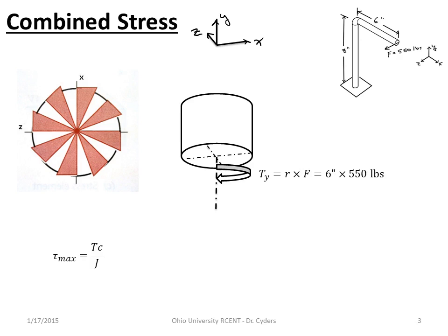And for a round shaft, circular cross section, the torsional stress distribution, the shear stress distribution due to torsion, is maximum at the outside. It is constant regardless of where you look at it on that circle. Of course, it's symmetric, and so we would expect that. That makes sense. It's 0 at the center.